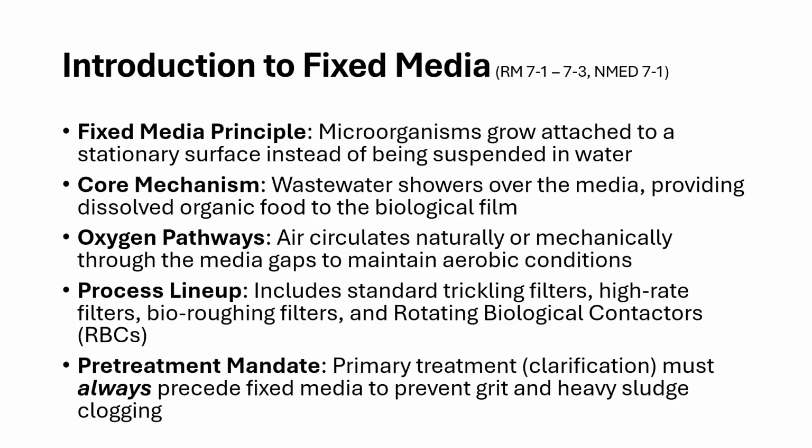Okay. So the fixed media principle is the microorganisms, or the bugs as we call them in wastewater treatment, are growing attached to a stationary surface instead of being suspended in water. So a bit of a different perspective. And what happens is we trickle or pour or shower the wastewater with its organic load over the media, so that dissolved organic food is being fed to that film, which is where all the microbes are hanging out. Okay, so a little different perspective.